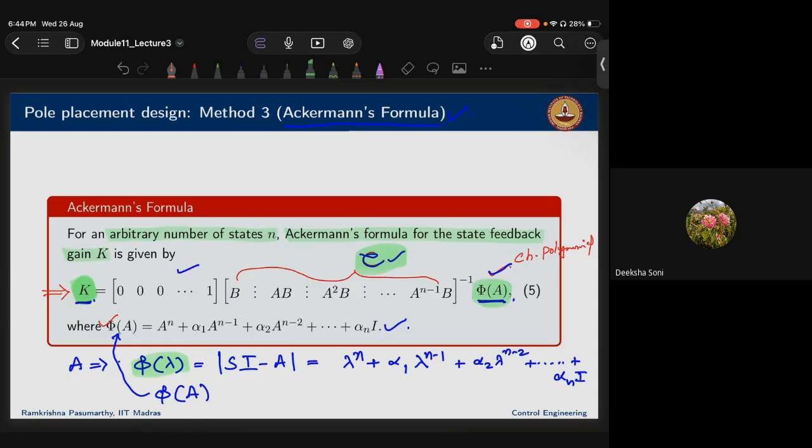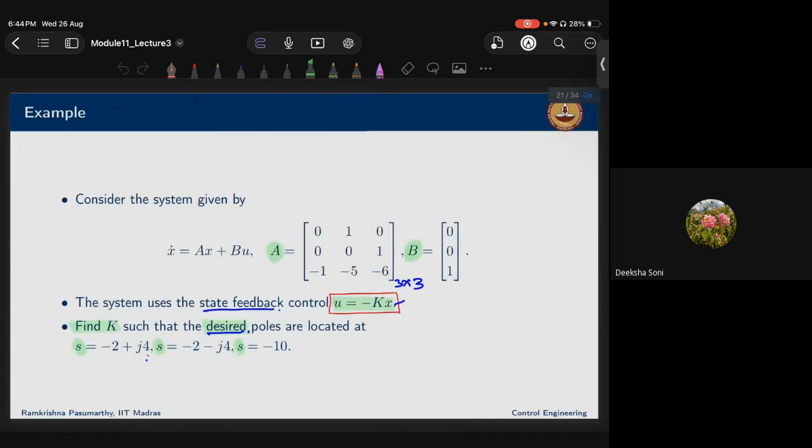You can use any method when the question is on the pole placement technique. The first one is simpler. The second one is for when the state space equations are in CCF form. The third one is based on the Cayley-Hamilton theorem. You can use any method.